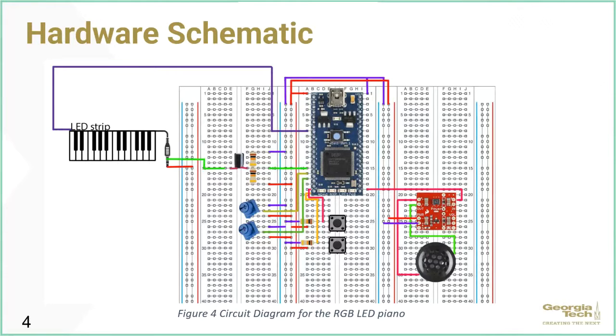The key components are the big LED strip on the piano keyboard, a stereo jack coming from the piano for the analog signals, and the big blue device that we see is the Mbed LPC 1768, which will be our microcontroller, which will process this analog signal coming in, and then goes back and lights up the LED on the piano, as we see based on the purple wire coming out of the device.